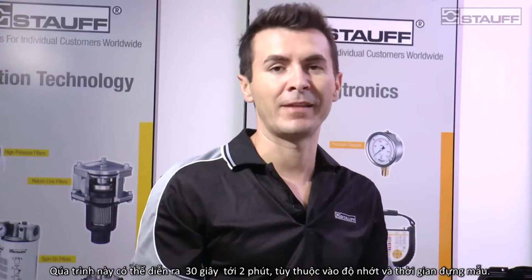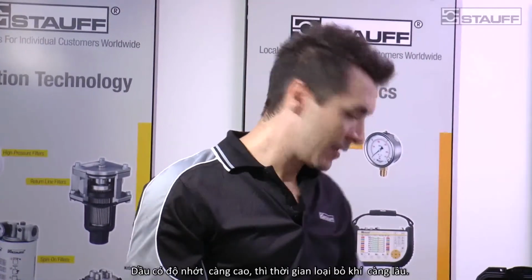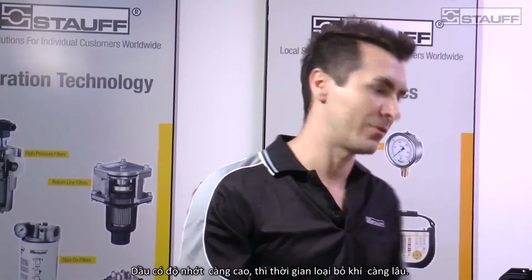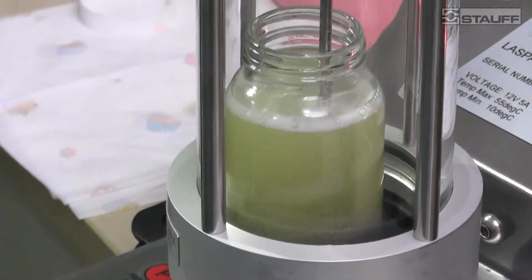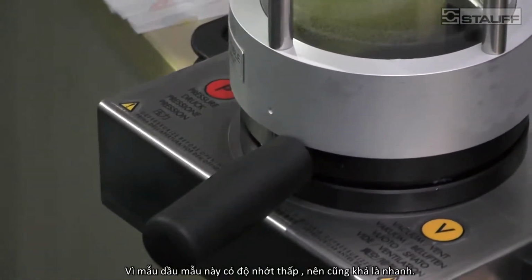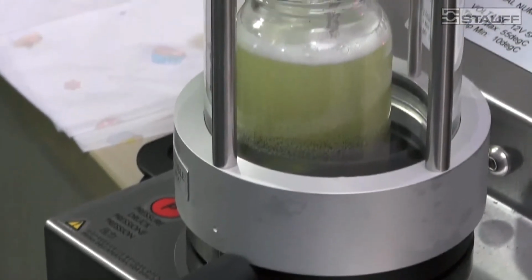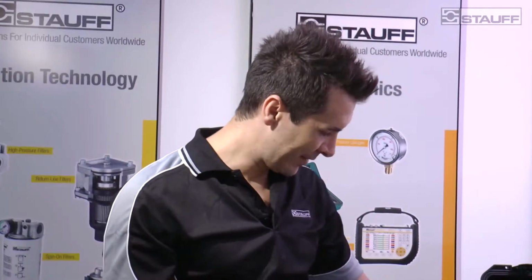This process can usually take 30 seconds, a minute or two, depending on how thick the oil is, or depending on the viscosity of the oil. High viscosity oils will take longer, low viscosity oils will take shorter time to remove all the air. So you can see all the bubbles. Because this is hydraulic oil, it's actually going quite quick. You can see.